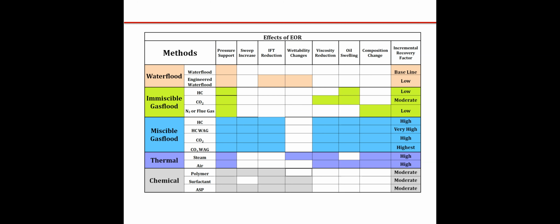These are some particular types of polymers, but most commonly it is used as a precursor to alkali surfactant polymer fluids to modify the existing water flood, cut down on those fingers, make the flood front more or less stable, piston-like, and get some easy oil to be produced.